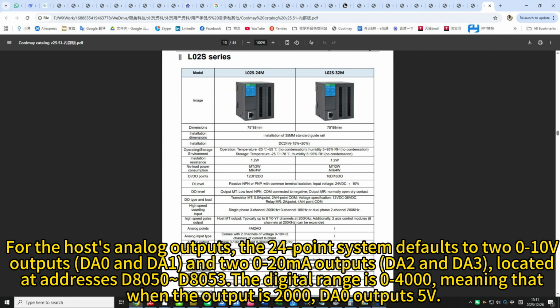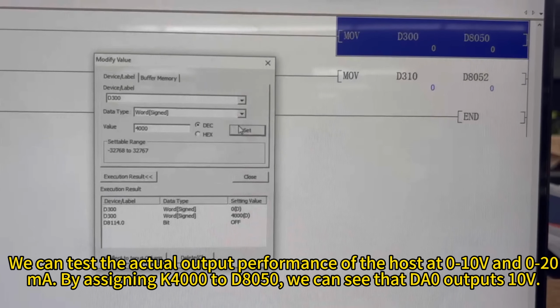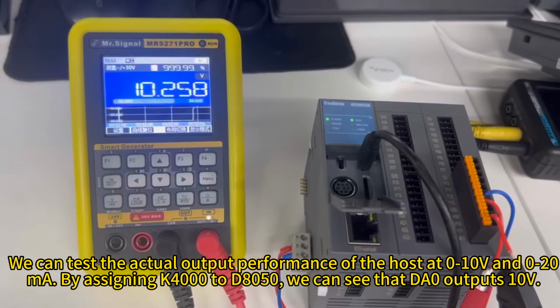The digital range is 0-4000, meaning that when the output is 2000, DA0 outputs 5 volts. We can test the actual output performance of the host at 0-10V and 0-20mA. By assigning K4000 to D8050, we can see that DA0 outputs 10 volts.